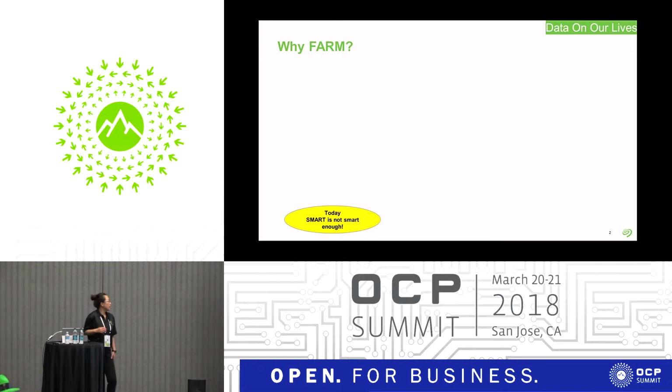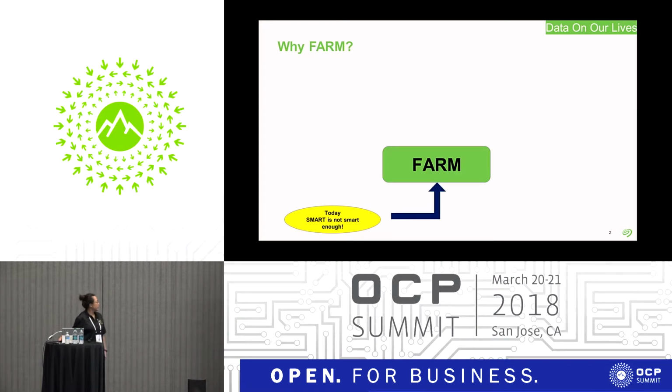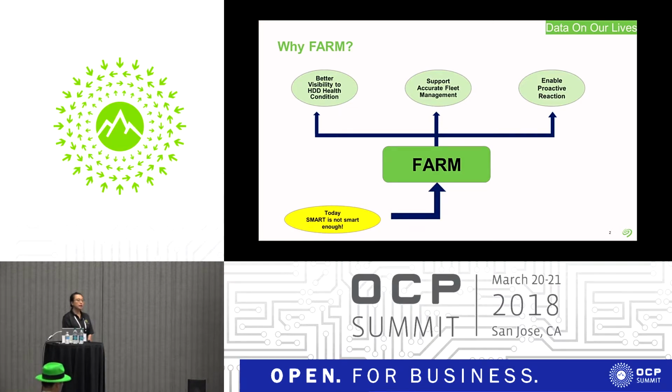So we will say what is FARM, right? As a vendor, we constantly hear something like SMART today is not smart enough, right? So are there any ways we can provide more information for the host side to do fleet management? That's why we provide this FARM log for our customers. The point is to see whether we can give you more meaningful, useful information to the host to do better drive health condition monitoring. Also, give you accurate information. You can do some proactive fleet management, right? That's the whole point.